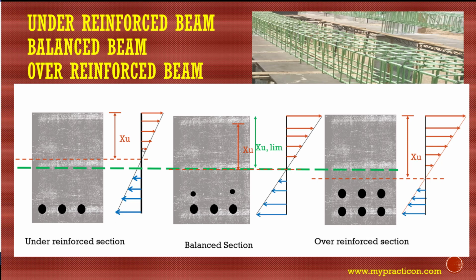So now come to the strain theory. When an under reinforced section is used, the name itself says under reinforced, the reinforcement is lower than the balanced section. Obviously, when the section is loaded, since the reinforcement is low, the strain reaches its maximum first in the tension zone, which is the reinforcement. Later, the compression zone will reach its maximum strain, which is normally 0.0035, at a later stage. We'll discuss the crack theory in the next slide.